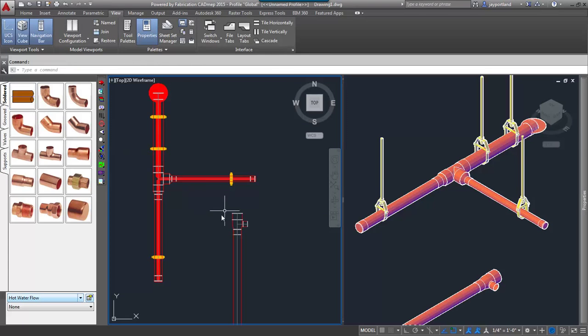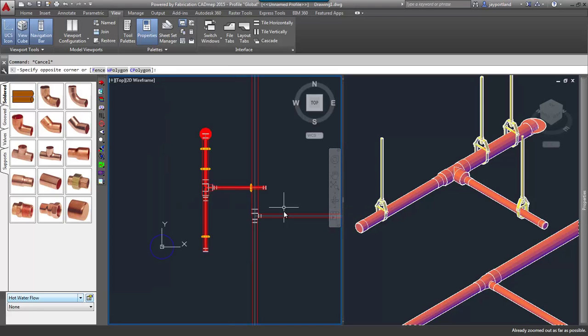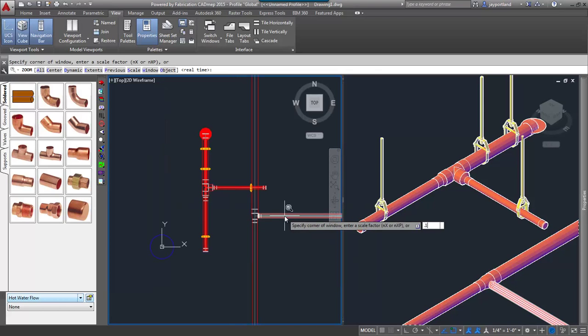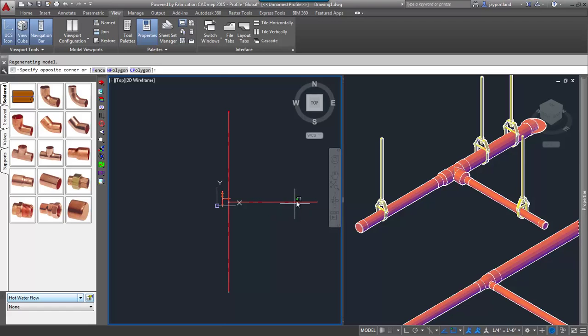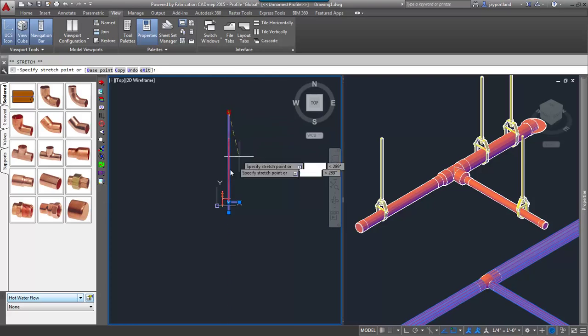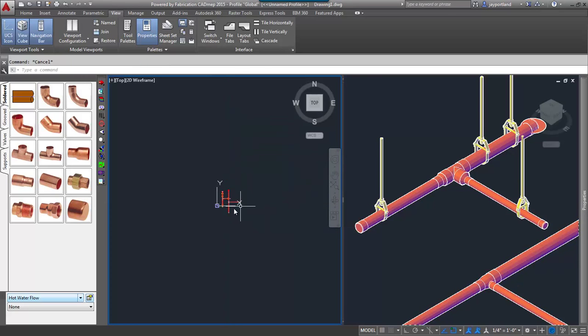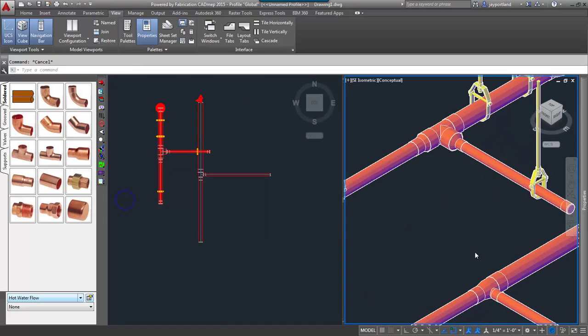Let's add some pipe. And by using the attacher method, we can add pipe to all 3 sides. Now, had I been smart, I would have held the control button and selected the right length, maybe 12 inches. But, no matter. I can come back and just use the grips and pull this back so it's shorter. But that's a tip for you. Hold the control button when you pick one of those tools. It'll give you the option to dictate the length.